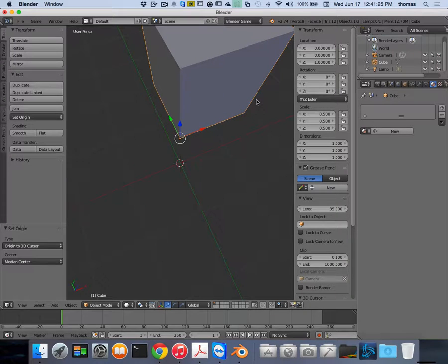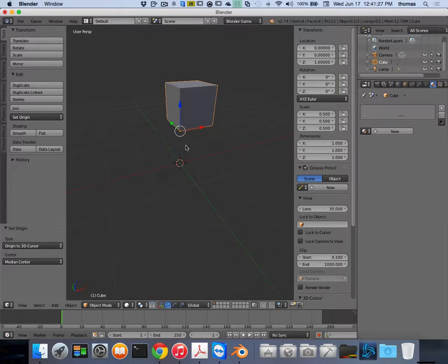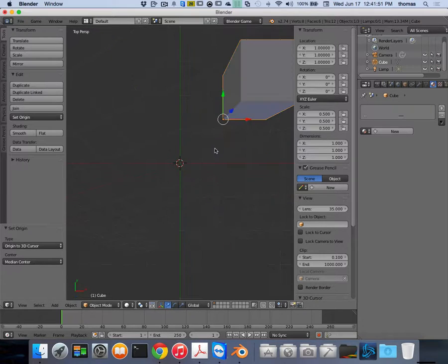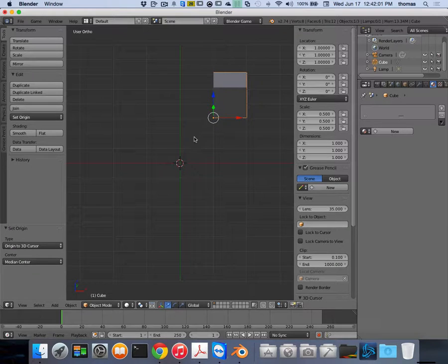I'm going to zoom out here so you can see that that's exactly 1 unit up. And if I want to go 1 forward across the y-axis, as an example, I can just go y, put exactly 1 unit. And if I want to go right 1, that's 1 across. Then, as you can see from the top view, it's exactly where it should be. So it went 1 up, 1 across, and it always uses this bottom left-hand corner to deliver that exactness.